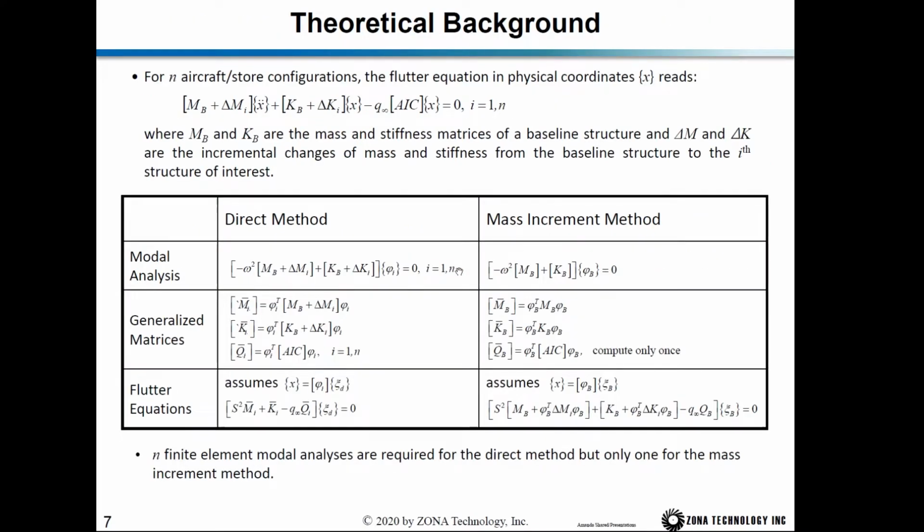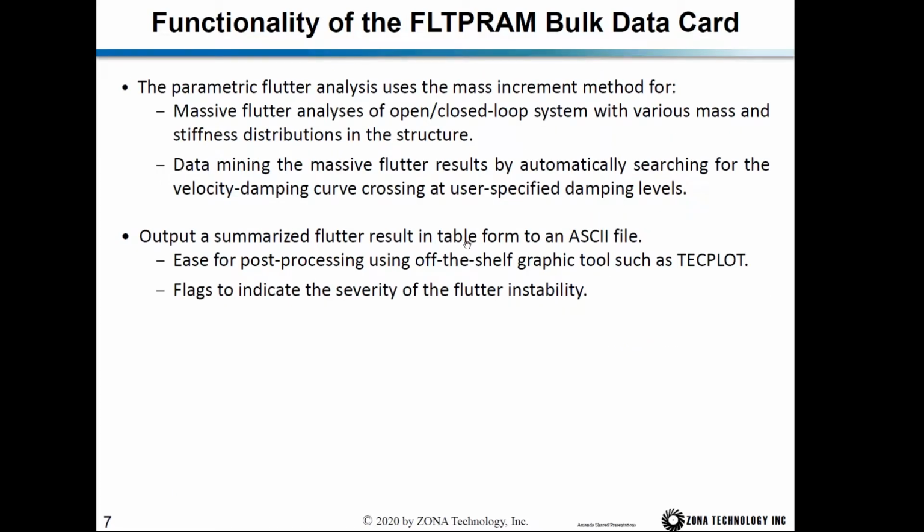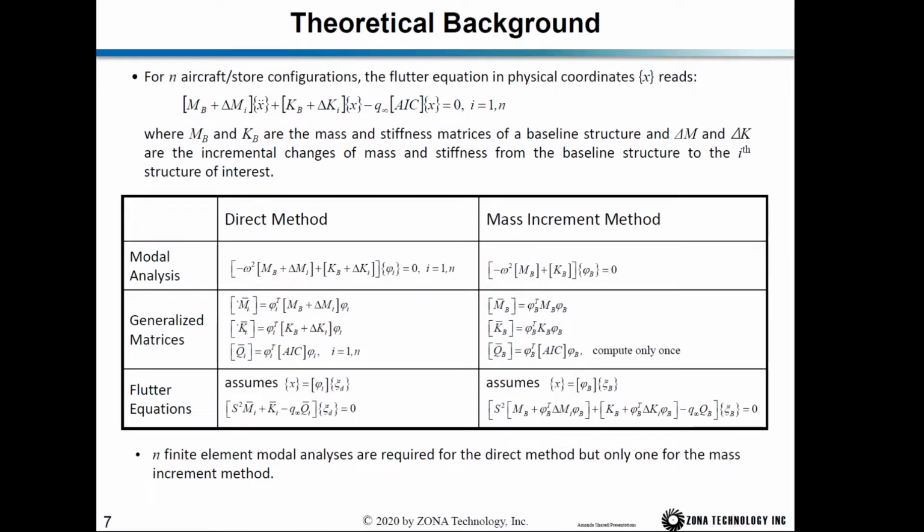So the FVM card module can perform thousands of flutter analyses of each aircraft with the store configuration in one single computation. And then you will output a summarized flutter result in table form. Okay, so you can easily look at the flutter solution of each store case.